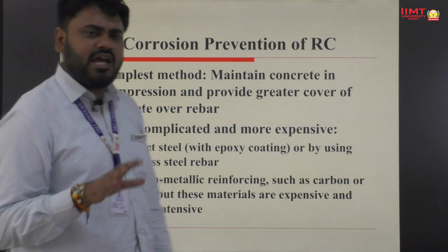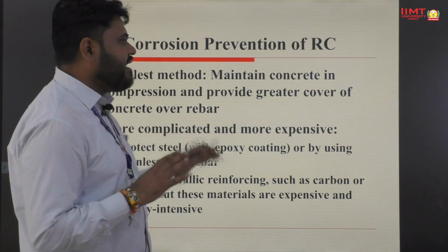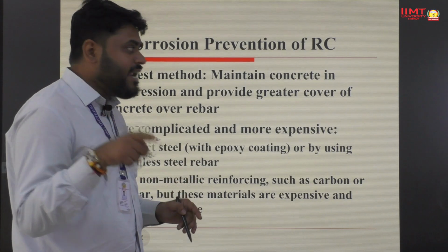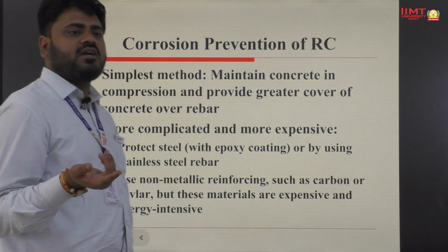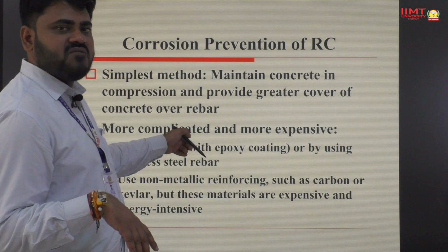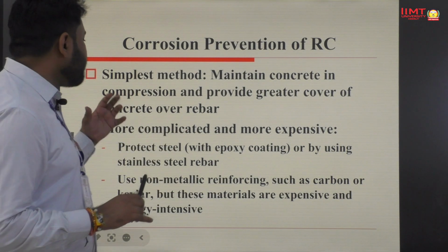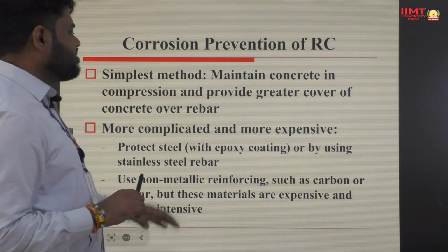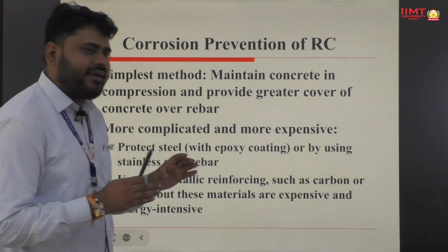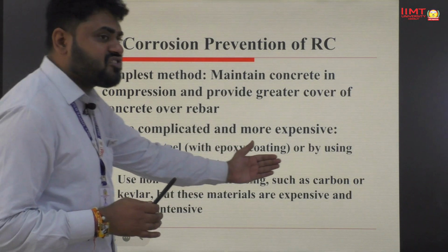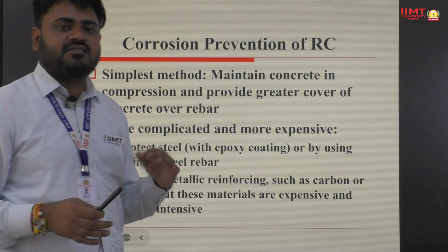For any type of structure we make in designing reinforced cement concrete, we have to be aware and maintain the concrete in compression and provide greater cover. Even if it is 25 mm, we have to make more cover to protect the rebar. More complicated and more expensive: we have to protect the steel with epoxy coating or by using stainless steel rebar, or use non-metallic reinforcement such as carbon or glass, but these materials are expensive and energy intensive.